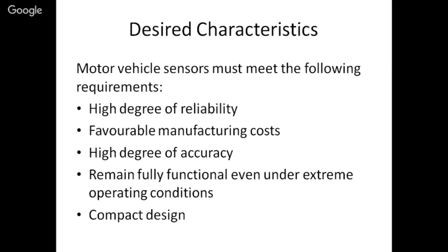Now as the vehicle is moving on a road, the friction conditions or the traction between the four wheels and the road is different for all the four wheels. So when you apply brake, by default the same braking effort goes to all the four wheels. Now let us say under one wheel there is some oil or something, so the traction between that particular wheel and the road is less. So that wheel will come to a stop early as compared to others, resulting in the skidding of the vehicle.